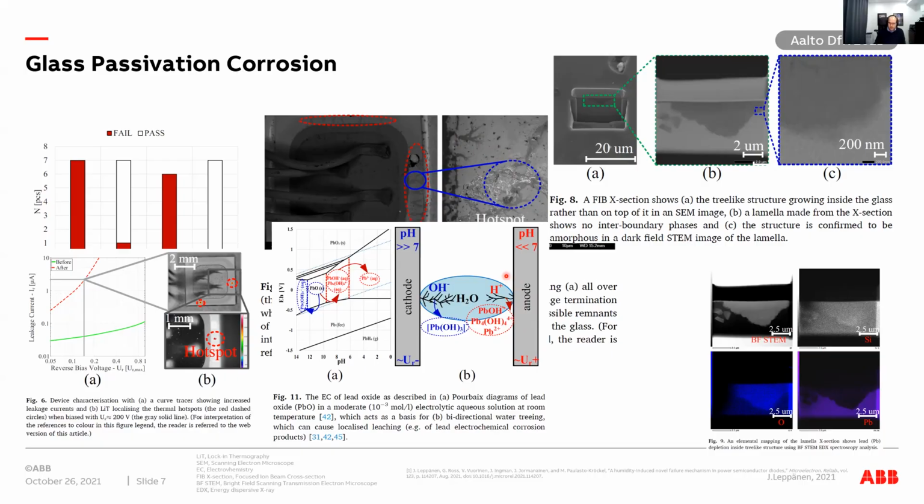There they have even much higher electric fields, and it's similar to partial discharge, where electrical treeing is also common. So this is really a similar phenomenon: the water will agglomerate into the surface, and we have a high electric field there.